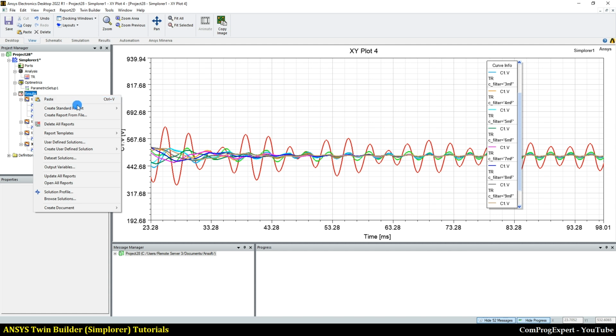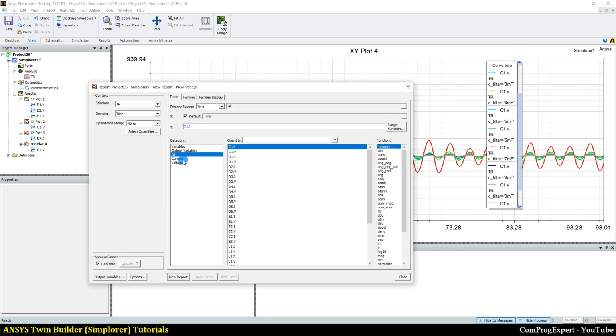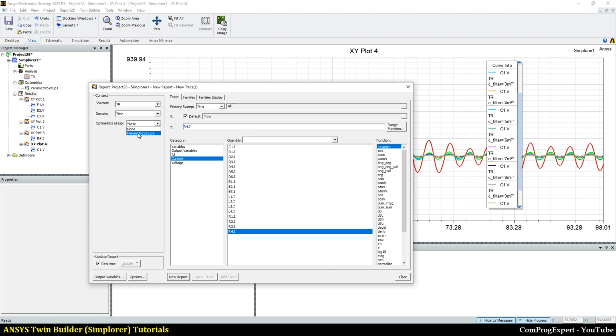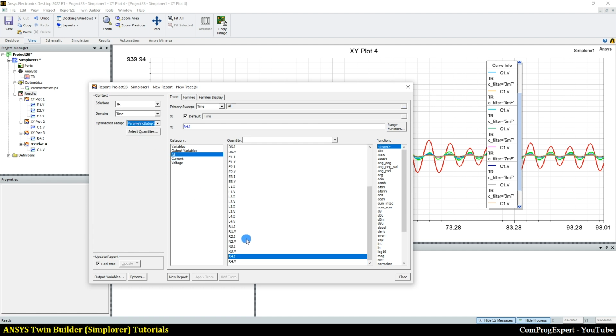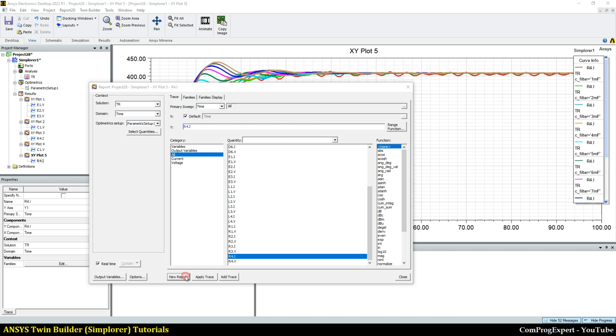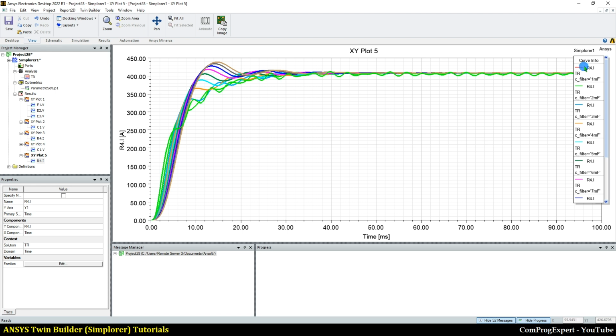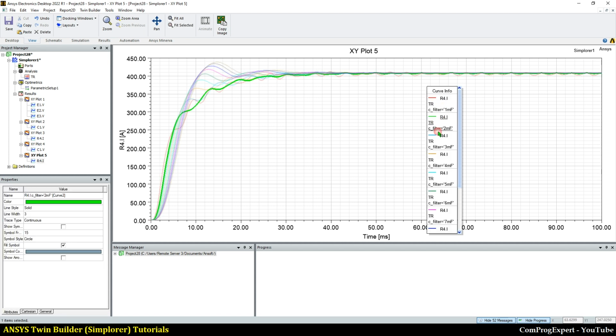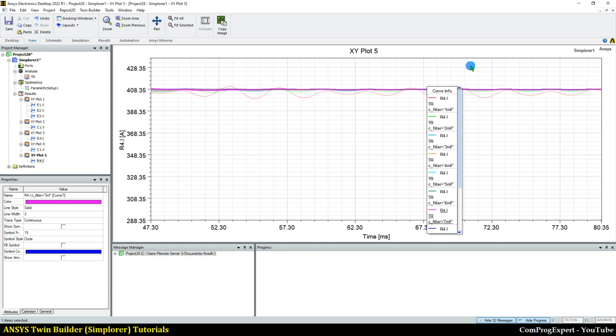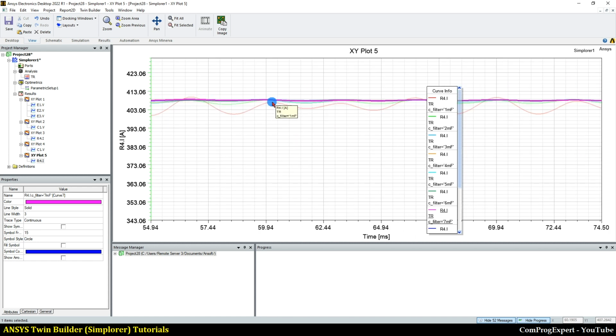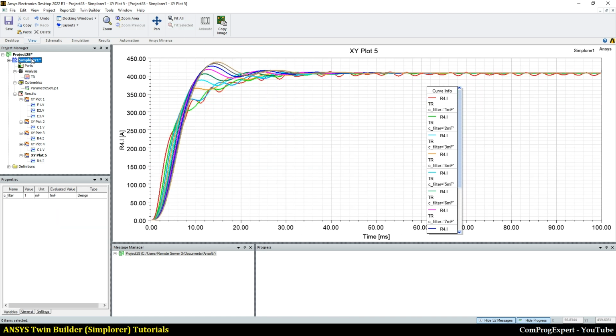And you can plot also the value of the load current versus capacitor value. As long as we increase the value of the filter capacitor, we have a DC current, right? The ripple of the current is lower and lower.